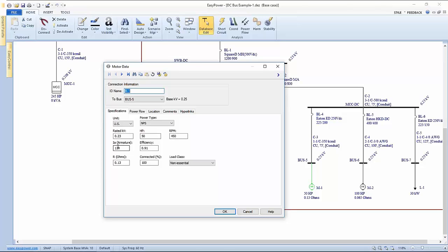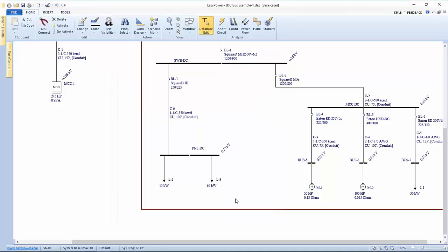Frequently, you need to look up the armature current, but most importantly, you need to come up with a resistance value for the armature. And this is what we came up with an estimate on, again, for a 230 volt system. And if you notice on the curve, the plot was fairly flat between 20 and 50 horsepower, so we used essentially the same resistance.